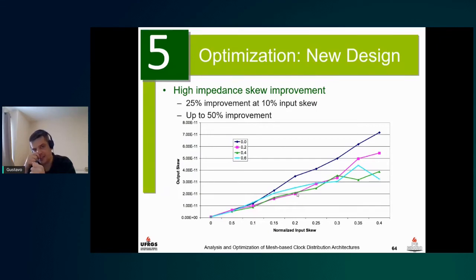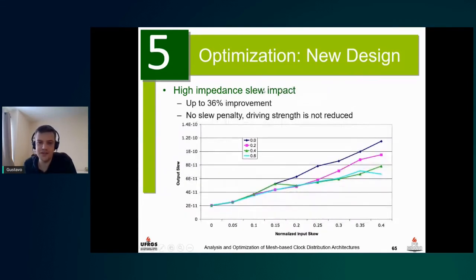It's better than having just the late buffer switching late. We are kind of making it so that when the late buffer switches, we already have a little bit of charge in the load of that buffer. But better than that would be a case where, when a buffer starts to switch, it doesn't find any resistance from whoever is late. And that explains why we are seeing a smaller clock skew. For the same reason, it also leads to an improvement in the clock slew.